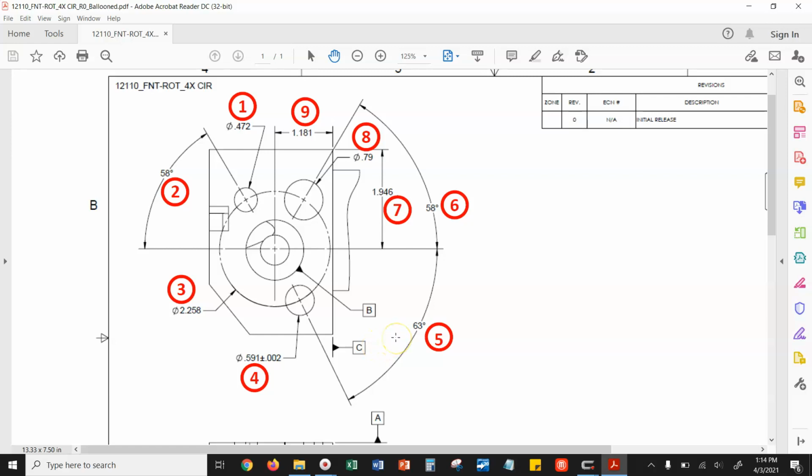A lot of times they come in as negative when they should be positive, or they're coming off the x-axis when they should be coming off the y, or something like that. Same thing with balloon 6 here, just another angle dimension. I do see that with balloon 7, we need to touch this back edge here at some point to be able to output the distance from, I assume, I don't know if that's the center of the bolt hole pattern or the center of the datum.